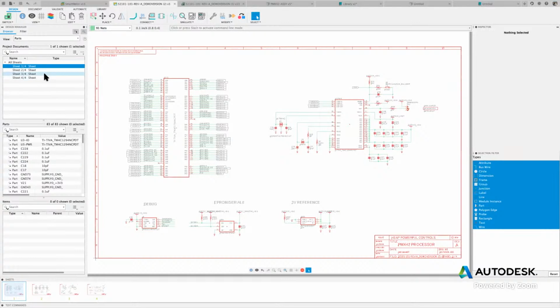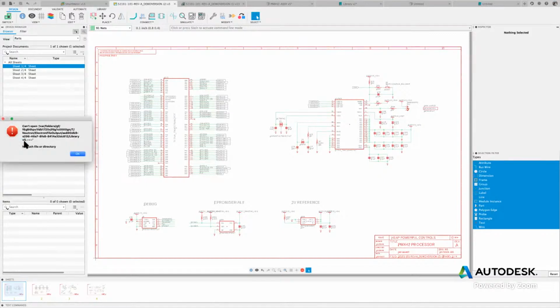Now, let's talk a little bit about these screens that you see on the outer layers here. These are panels. These are very useful information panels. I could categorize it by parts, by groups if I have groups defined, or by signals or by nets. So if I need to find a part, you could actually type in the parts here. So I just type R1, and it's letting me know where R15, R11, and R16 are located.